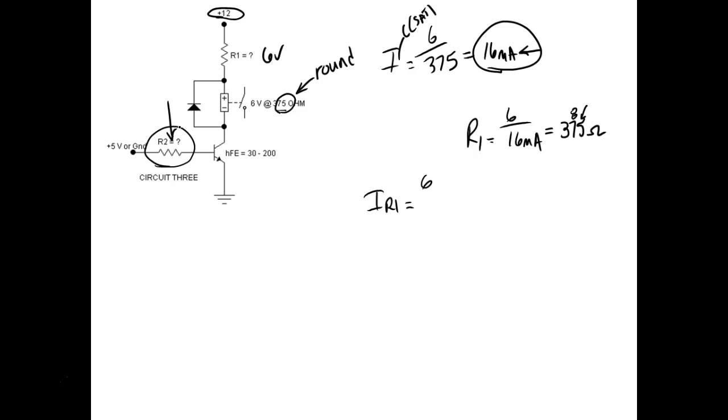So what's the next standard value above 375 ohms? 390. So that'd be fine, 390. That's really, really close. So 3.8 compared to what? 3.9. We're really, really set on this guy. So we'd probably use a 390.